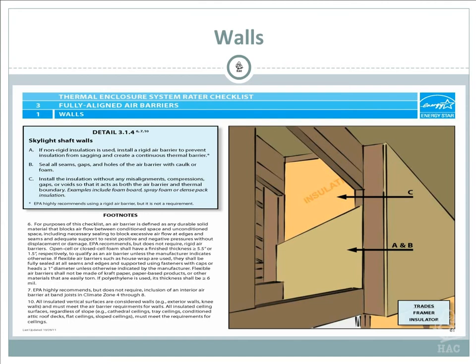And again, you want to seal all the gaps, cracks, and anything like that, because remember, that sheetrock covering the skylight is only 5/8 or 3/8. Again, with skylights, you have to work in the attic, so do it early, before you spray.